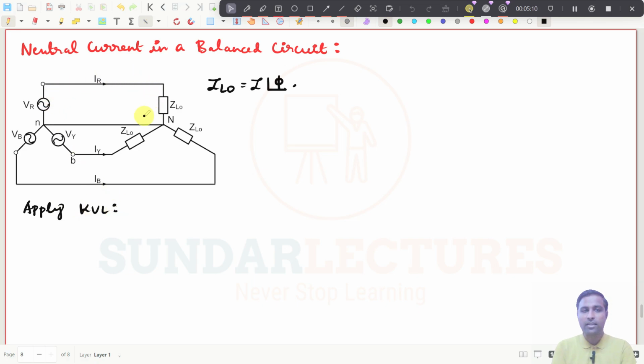For each loop, for example, for this loop, if you are applying KVL, make this plus and this minus. If you are going for VR, from minus to plus, you have to travel, right? So I am traveling from minus, in this direction. This current is coming opposite to me, so it will be IR into ZL, right? I have come to this point. So if you are writing IR, then IR will be equal to what? VR divided by ZL, which is nothing but Z at an angle of phi.